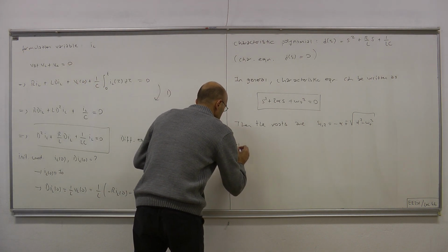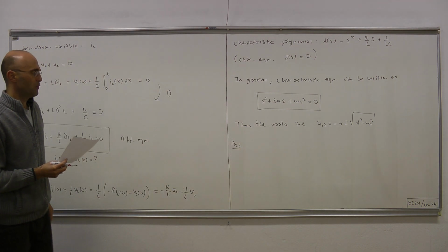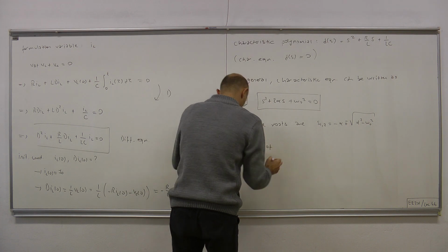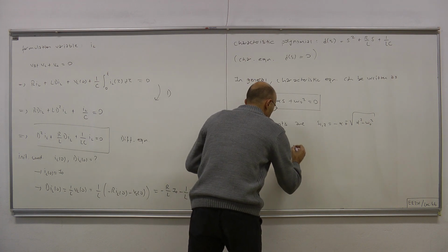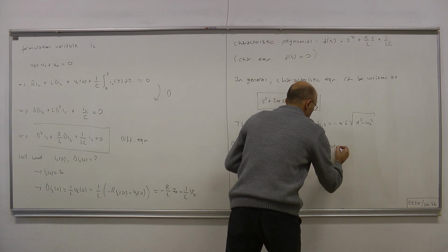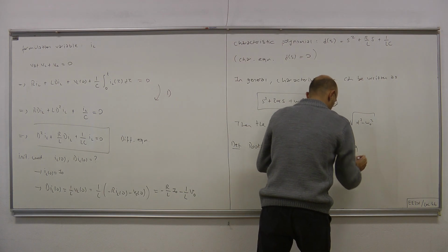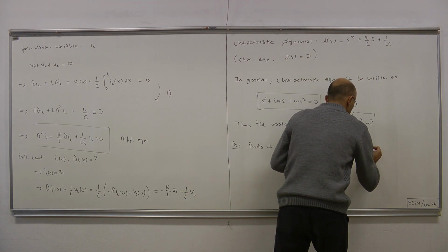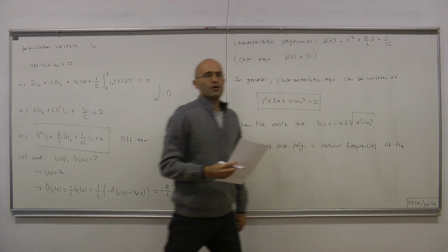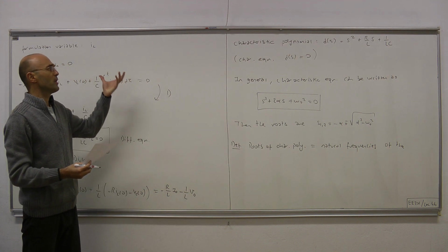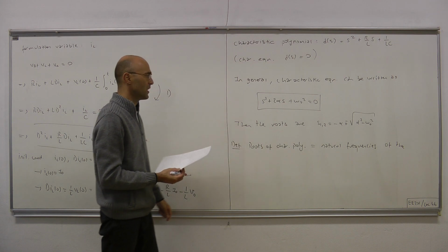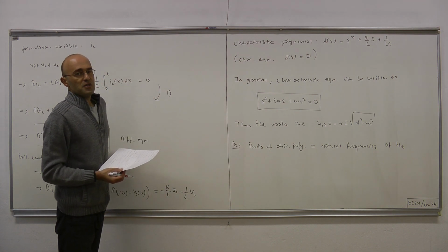Now we introduce important definitions that we will be using a lot. Roots of the characteristic polynomial are what we will be calling natural frequencies of the differential equation, and since no matter what formulation variable you choose, you will always obtain the same differential equation with the same coefficients, those are also called natural frequencies of the circuit.